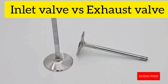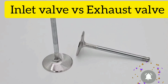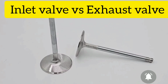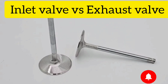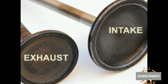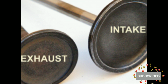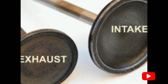We have two types of valves in an internal combustion engine: the intake valve and the exhaust valve. An intake valve allows fresh air to be admitted into the engine, and an exhaust valve allows burnt gases to be sent out of the engine. In next videos, I will explain why some engines have more than one intake valve and more than one exhaust valve. What you have to keep in mind is that the head of an intake valve is wider compared to the head of an exhaust valve.